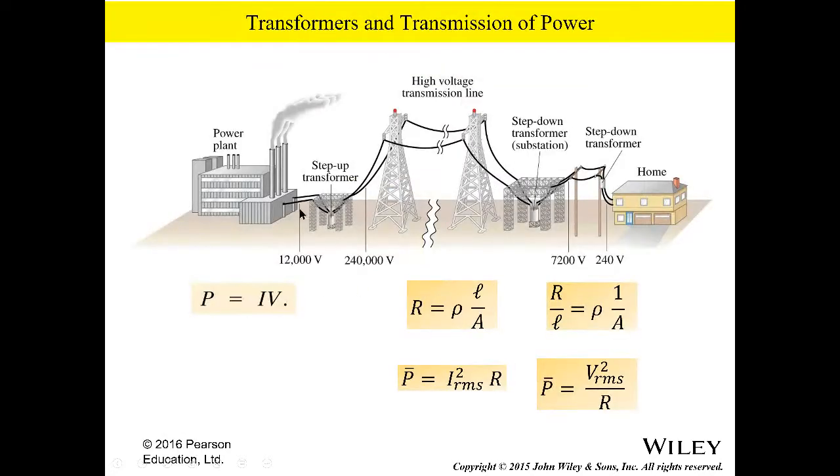They raise the voltage in order for this transmission not to lose money. After all, they spend a lot of money generating this electricity. Let's say they have generated 100 megawatts, but if 50 megawatts is lost on the transmission over 400 miles, then they can only earn based upon half of it. So the power industry wants to be sure that the loss is not big, because you have minimized this current I.